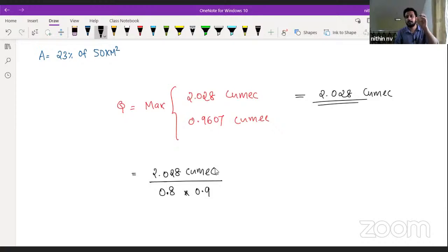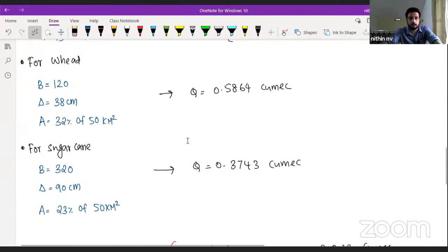Time factor means the actual period of the watering period that will come in the denominator, what we have actually been given. So if for 1 day it is not operating, that means 9 days by 10 days of total, which means 0.9. Clear, what is time factor? So if they are giving that in the question,